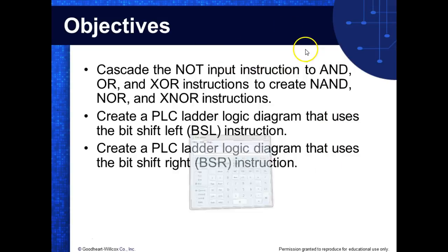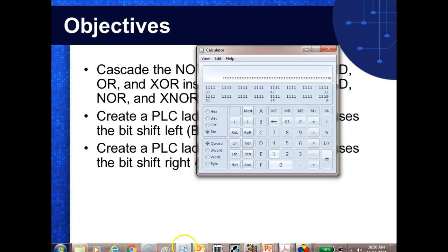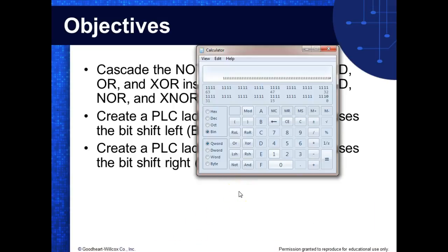So I don't know what this guy. Oh, it says quad word on it, Rich. Oh, it does. Put it back up. See it right there, lower left, quad word. Oh, okay, yeah, quad word. So this is a double quad word with accordion. Of course, the Allen Bradley PLCs only deal with what Windows Scope refers to as a double word, which Allen Bradley calls a long word, which is 32 bits.